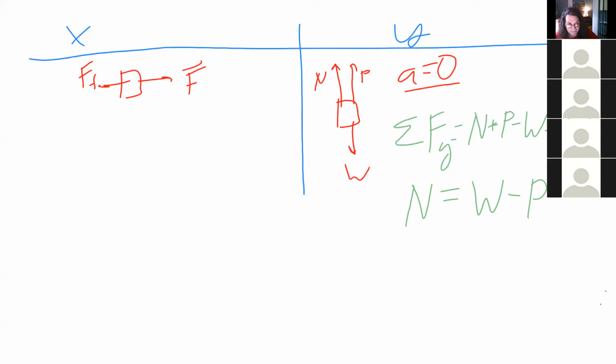All right, so for this problem, we could go ahead and calculate our normal force explicitly. And since we're just doing part A here, let's just go ahead and calculate that. So our weight is the mass, 2.5, times acceleration due to gravity, which is 9.8.